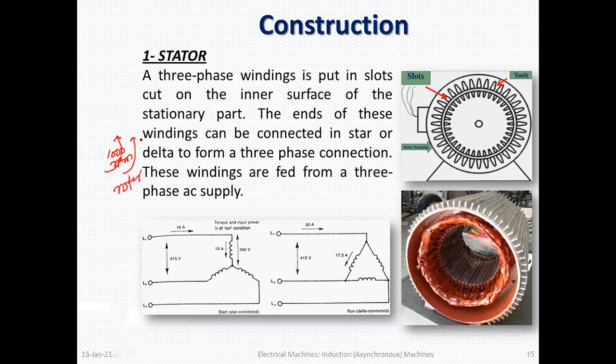So the machine momentarily will slow down. And once it slows down, again there will be a relative speed between the stator MMF and rotor, so the machine again will start to catch this speed. In this way the speed reaches 1000, then comes down; like that there will be a jerking, so the machine life will be in trouble.